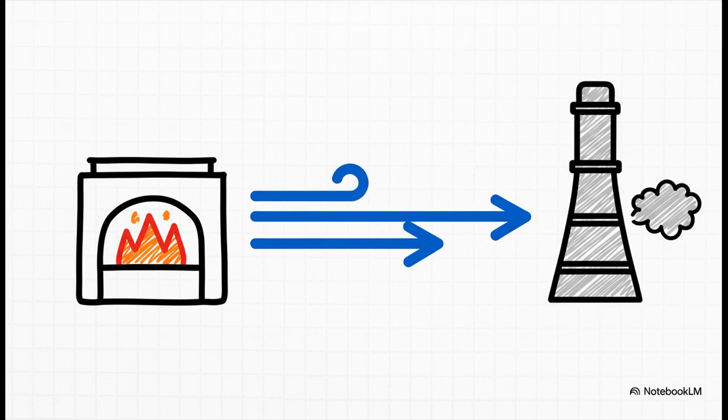This is a perfect example of what I'm talking about. It's one of the most fundamental, absolute golden rules of plant design. You figure out which way the wind blows most of the time, and you put your ignition sources, your furnaces and heaters, upwind. Why? So if there's ever a flammable gas leak, the wind carries it away from the open flame, not straight into it. So simple, so smart, and completely non-negotiable.